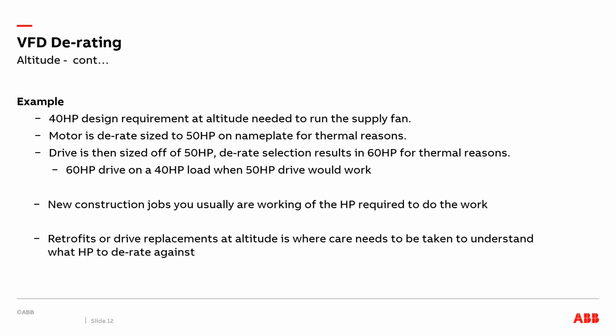Usually when we look at new construction jobs, you can see on the schedule that the engineers will usually call out what the working horsepower is required to do that work. So you don't usually run into this derate of a derate on new construction. It's more in these retrofits where we have to do our homework. When we're looking at retrofits, we want to make sure we're putting the right size drive on there and understand what the actual horsepower is of that working load at an altitude.